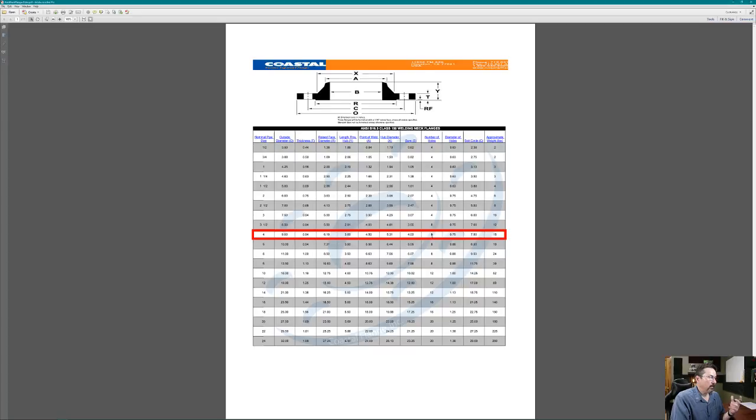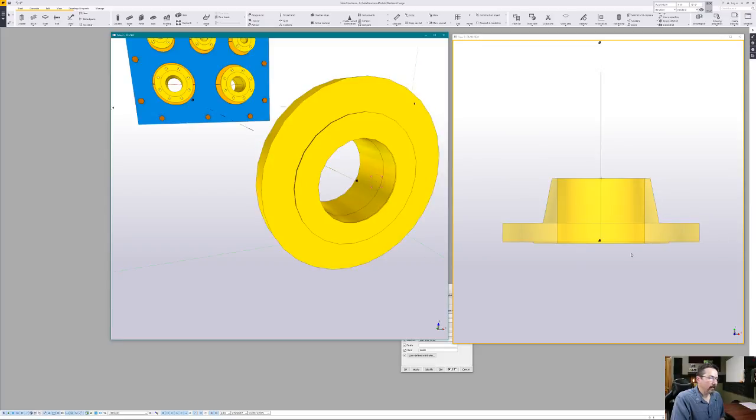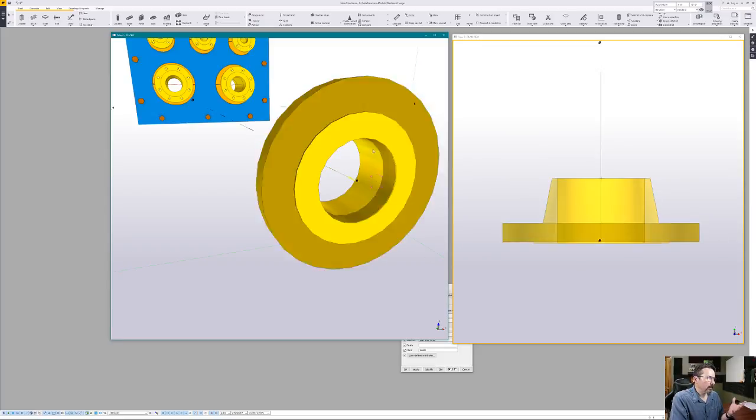On this flange there are 8 holes. They are 0.75 inch, or 3/4 inch, diameter holes, and the bolt circle, or the diameter to the center line of holes, is 7.5 inches. With that information, we're going to go back to our piece here, and now I need a clean view looking straight into the face so that I can put the bolts in.